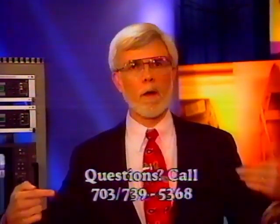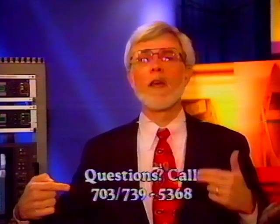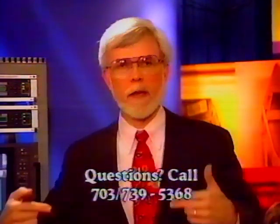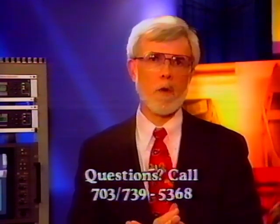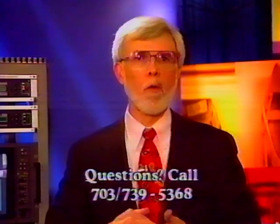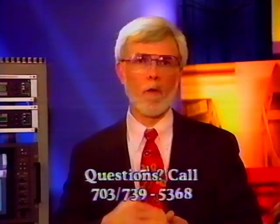We're using a very healthy symbol rate of 29 plus, and the forward error correction rate of 3/4 gives us the ability to restore down to a very low signal-to-noise level, Eb/N0.